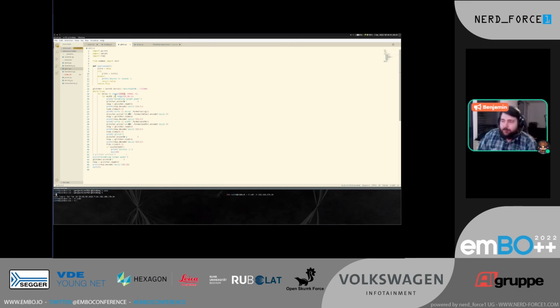And then we brute force how long we glitch it. And again, a bit larger than it should be, just to give us some additional chances. And as you can see, writing to the glitcher is really simple. You just turn off the device, you tell it how long the delay is, you tell it how big the duration should be, and in the end, you just tell it, go glitch.